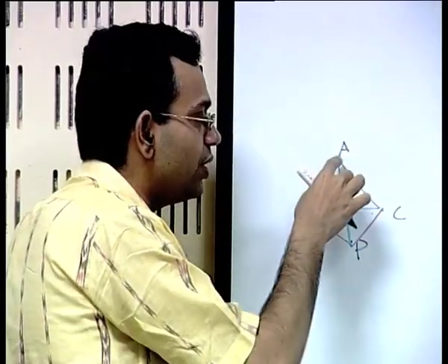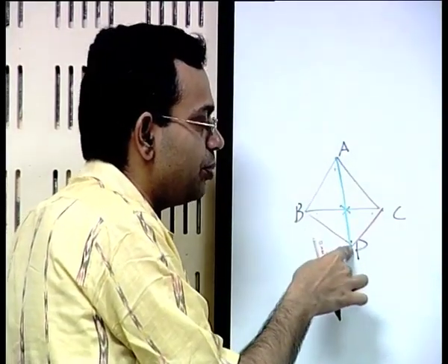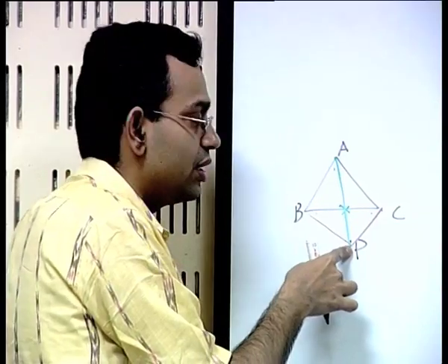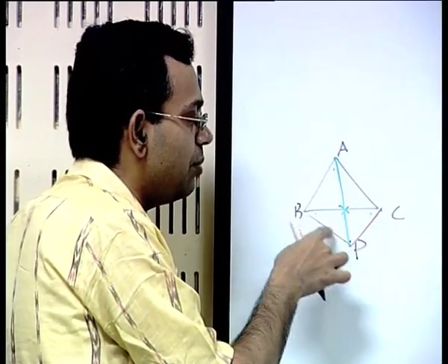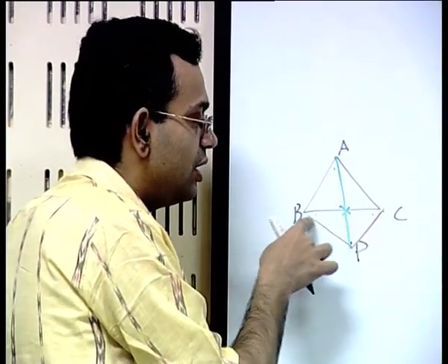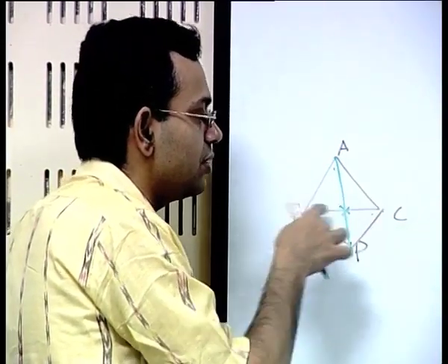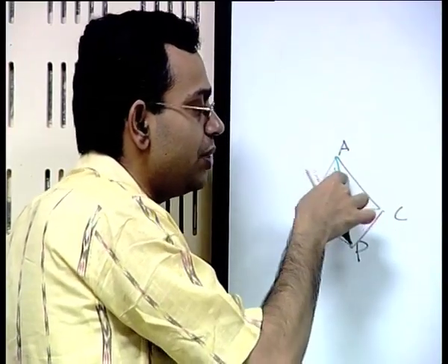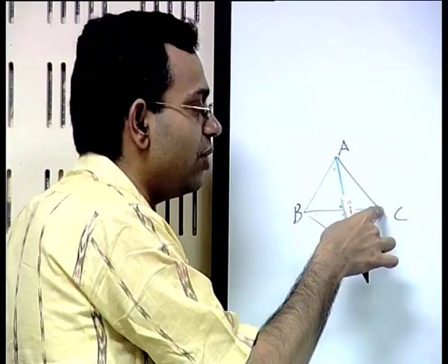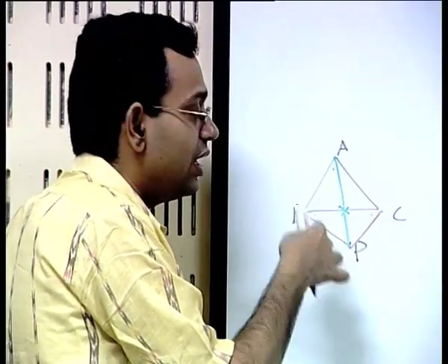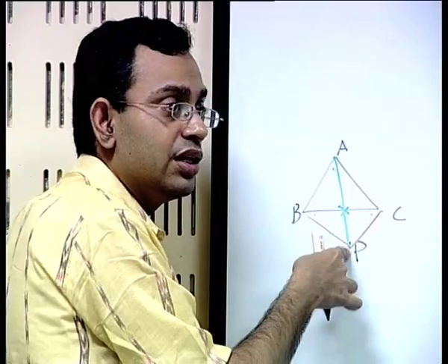So what you do is, when you consider the new point P introduced, you will have a quadrilateral generated A, B, P, C. It has a common line BC shared between the two triangles, that is one of the diagonals of the quadrilateral. If the new triangle is a bad triangle, you swap the diagonal.